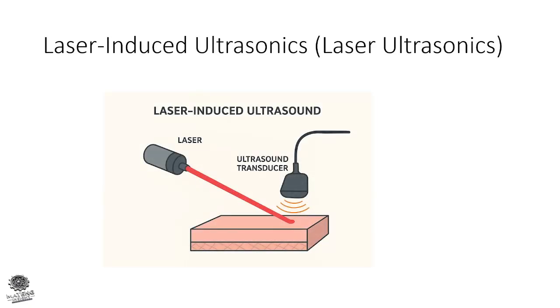Laser ultrasonics. Laser ultrasonics generate elastic ultrasonic waves in a specimen by pulsed optical excitation and detect returning waves with optical receivers such as an interferometer or laser Doppler vibrometer, LDV. It may be non-destructive, or applied with high energy and be destructive.